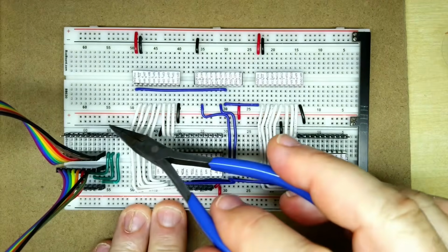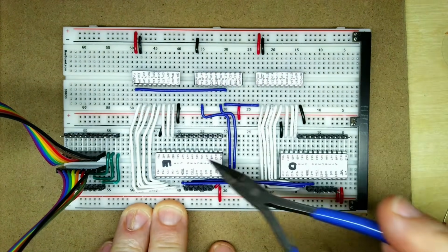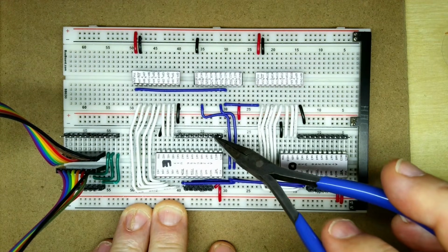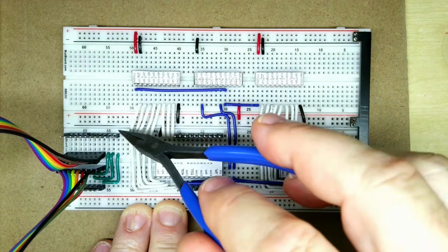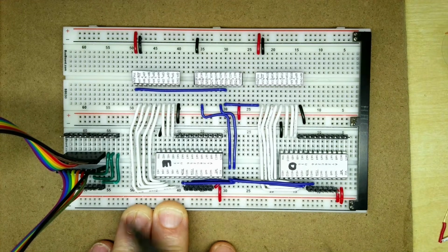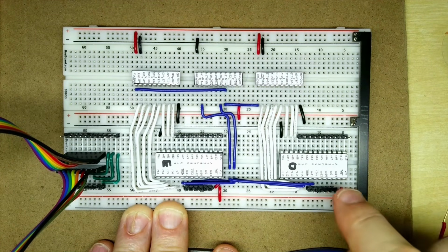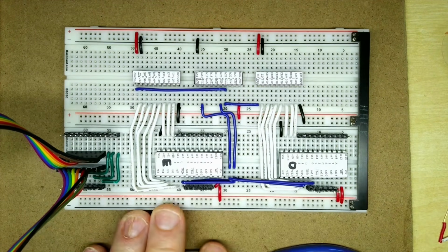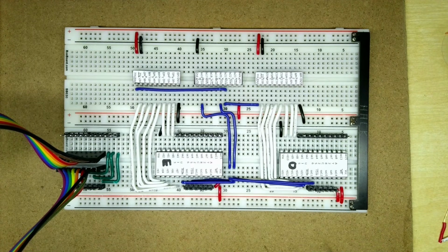So this means we just need to now go off and do the wire wrapping, connect SA2 to 7 to 8, 13, 15, all down to here. And then these ones here, we've got 9, 10, 11, 12 and 14 just need to go down to here. So not all of these will have connections. It just seems to be a lot easier. And then we'll use the wire wrap tool to go from there to there and from there down to there. I'm just going to go off and do that. I'm not going to record that on camera because it will take an hour or two. So when we come back, we should have all those things wired up. And then all we're going to need to do is worry about the extra control signals that go off to the rest of the board.